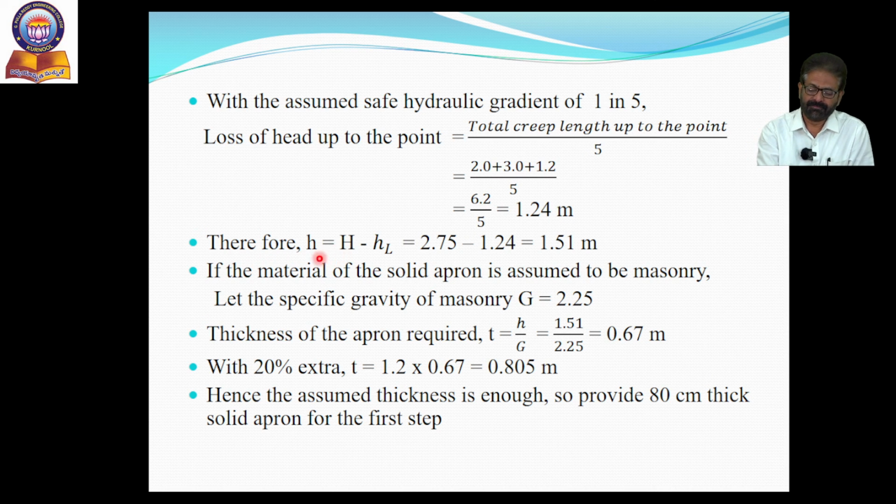Therefore, the residual seepage head is equal to total head minus loss of head. Total head is 2.75 as given in the problem, and 1.24 is the loss of head, which we just calculated. So this difference is 1.51 meters. This is the important data required for fixing the thickness of the floor.